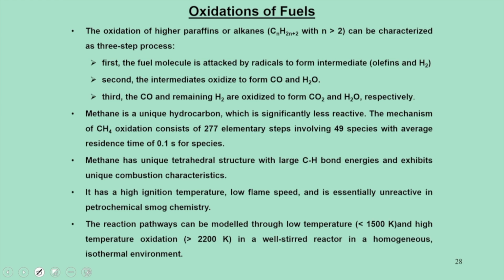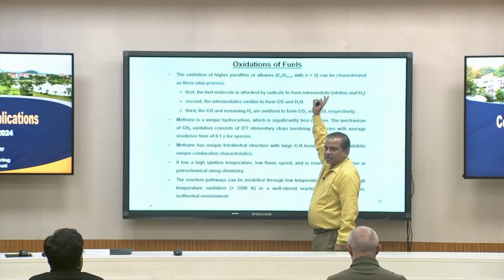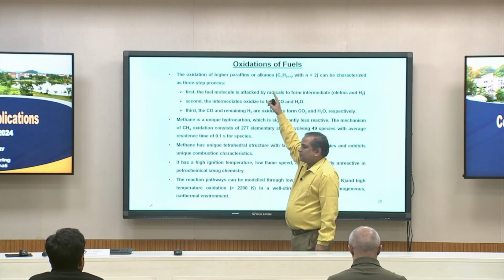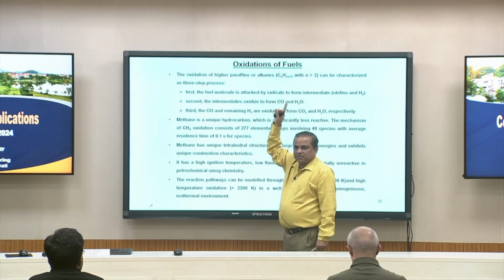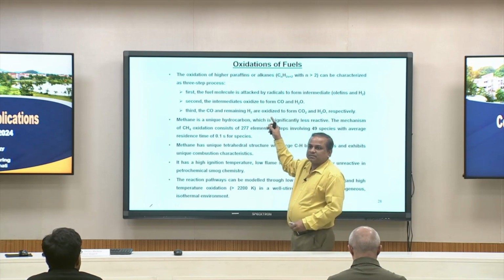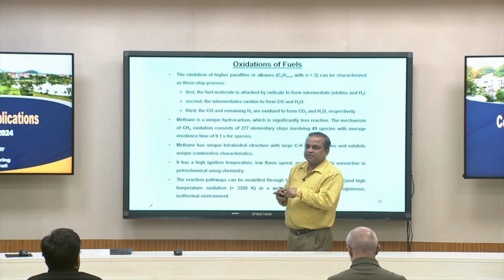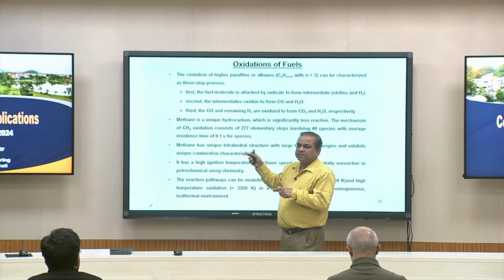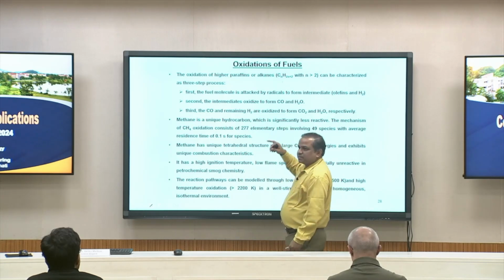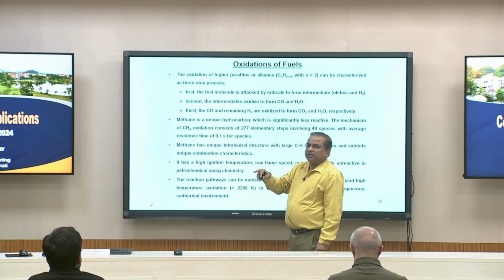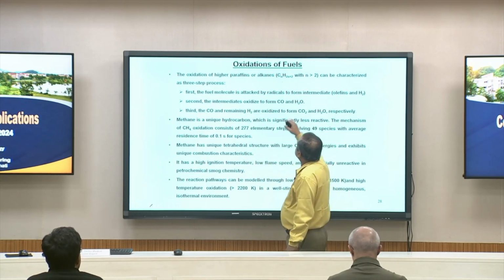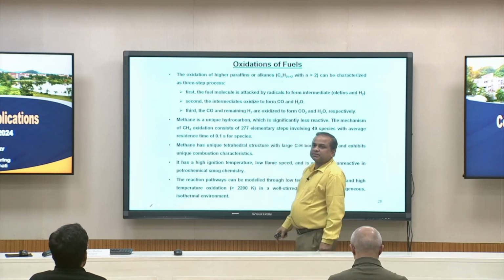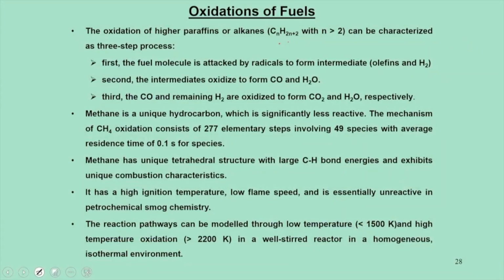So whenever we have these two terms, hydrogen has a good effect with oxygen because it goes to water, but carbon doesn't. Because of this carbon, temperature shoots up. When the temperature shoots up, air starts dissociating, so nitrogen effects dominate, and it gives NO2. Because it is a consequence of one event with the other, people are looking at how we can reduce carbon from the fossil fuel.